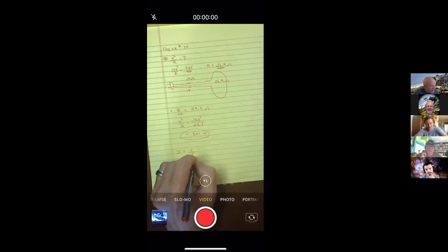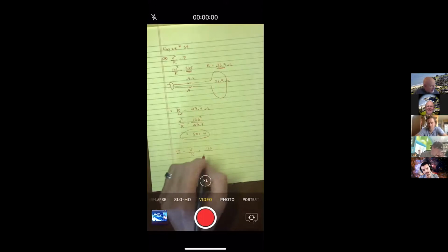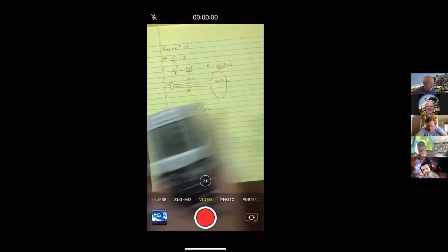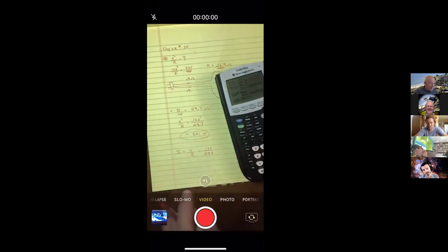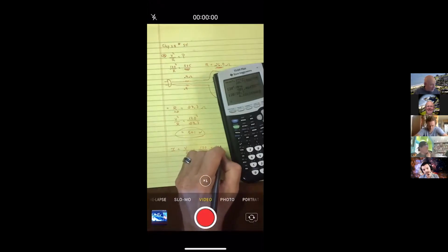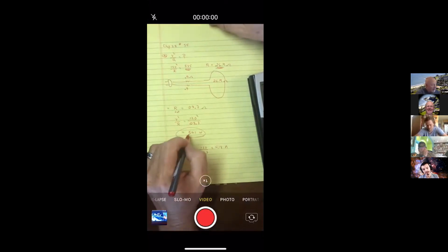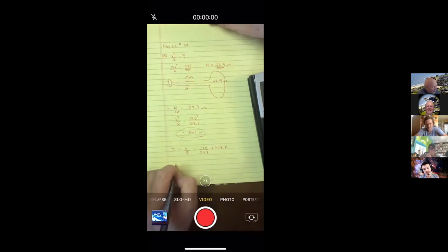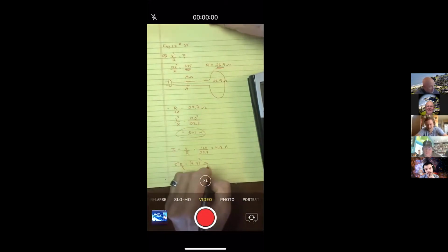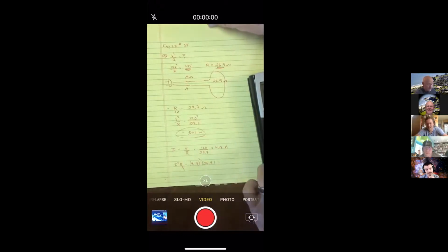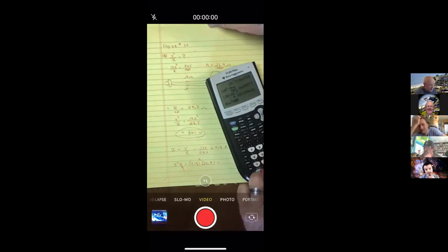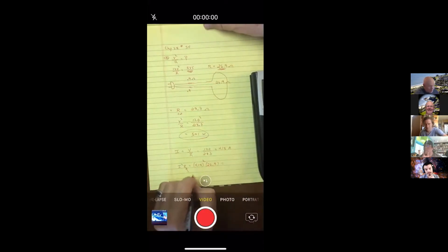So let's take voltage divided by the resistance. This is the 120 divided by the total resistance of 28.7. 120 divided by 28.7, and so this would be 4.18 amps. And to find out how much is going just to the vacuum cleaner, see, what I did was the total power. But I'll do this, I squared R. So 4.18 squared, and the resistance of just the vacuum cleaner would be 26.9. And so I will square that and multiply it by 26.9.